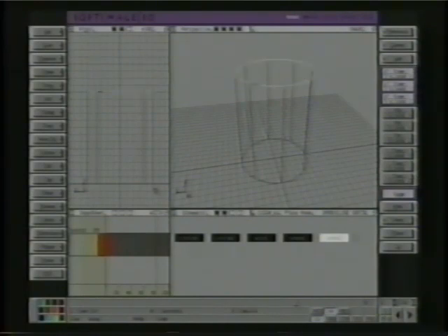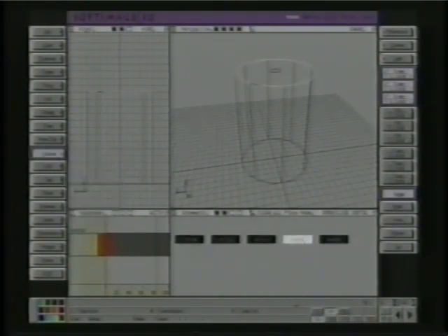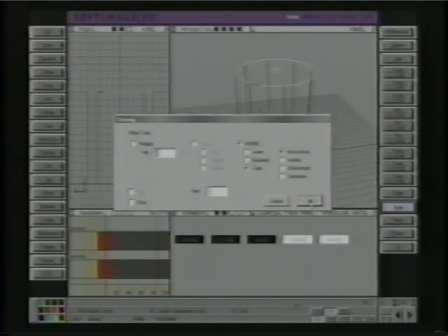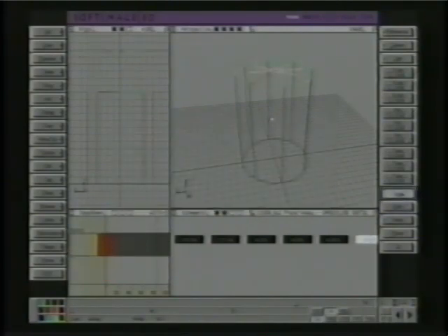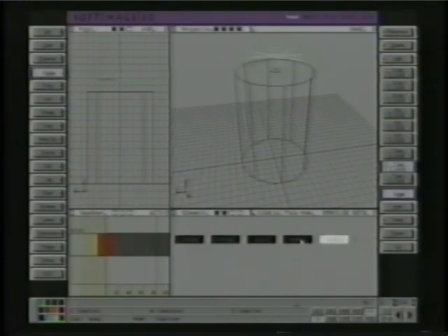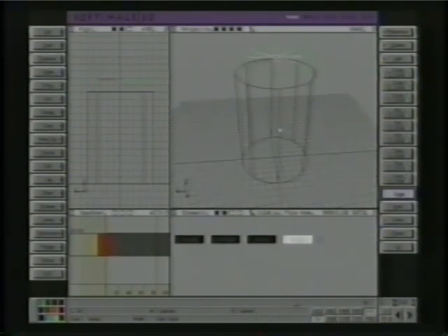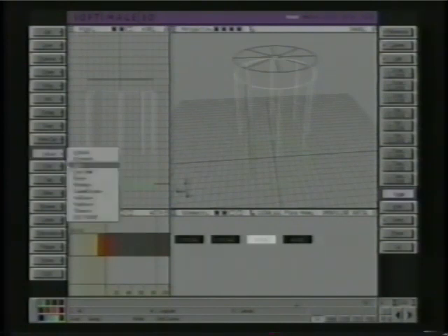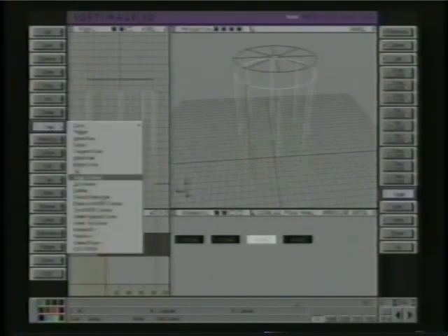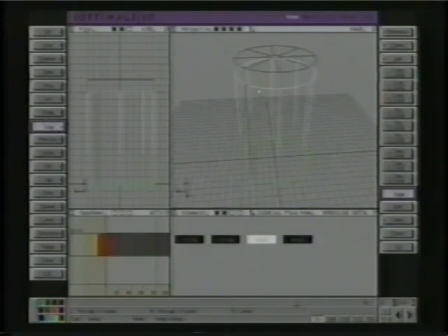Scale it in. Except before I scale it, let's do center to vertices so it scales right to the middle. And then I want to select that in the schematic window and do another skin. That. Right click, also cubic NURBS. I'm going to move that up so I can select its edge, and then I'm going to delete those other two curves. Select that, do draw, merge surfaces.